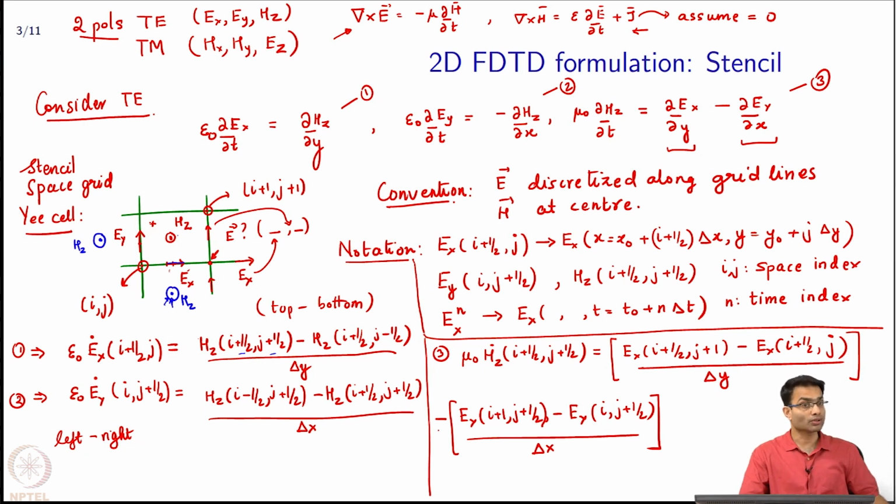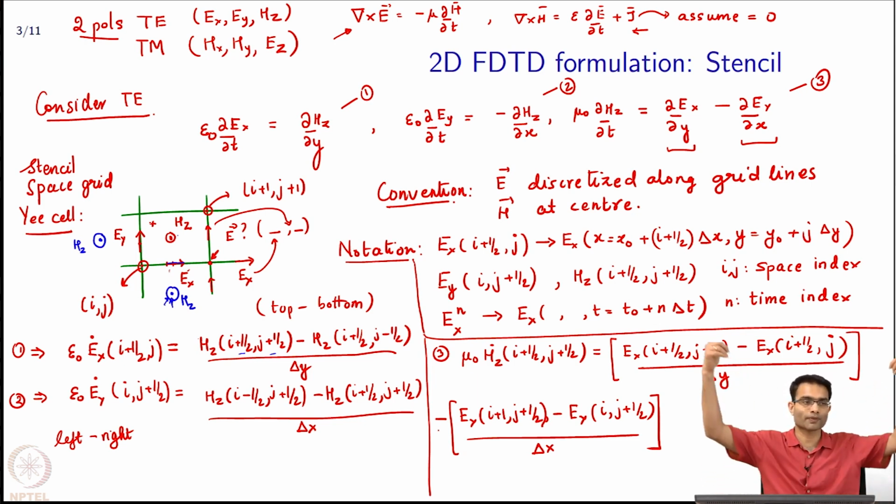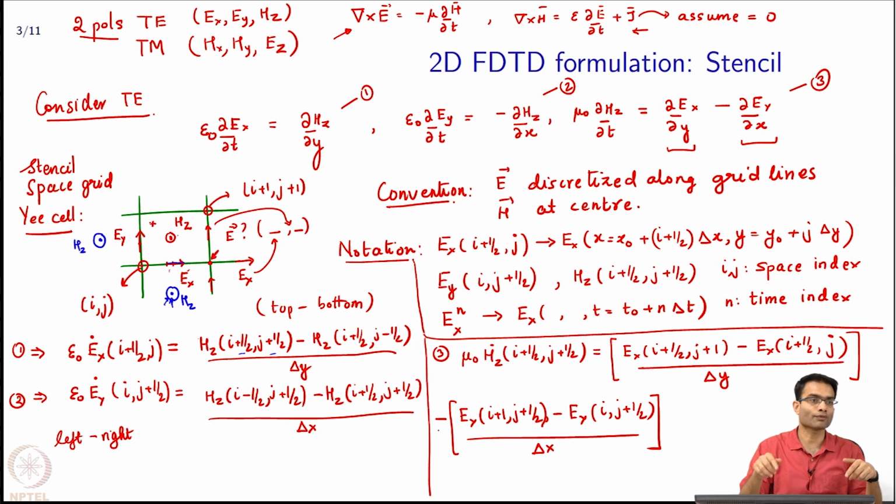This will also turn out to be quite a disadvantage of these finite difference time domain methods, because you have to discretize everything so finely. That's why these are called brute force methods. You brute force in space and time, calculating everything, even though finally you don't need it. In the radar cross section example, finally what do I want to know? I want to know the tangential currents so that I can apply Huygens principle to find the field everywhere. But when you do FDTD, I have to find the fields everywhere in space, and from that only take out what is along the edges. So there's a lot of work needed to get just one small thing.